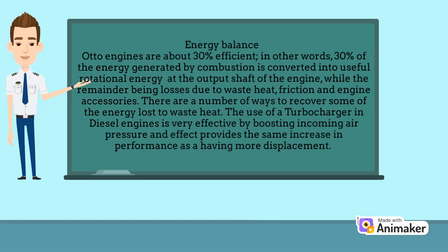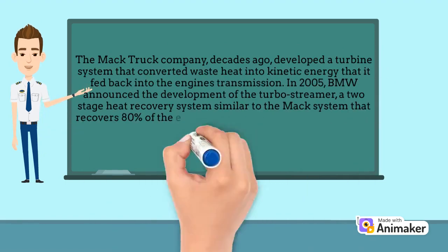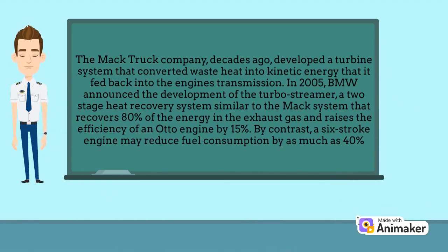There are a number of ways to recover some of the energy lost to waste heat. Use of a turbocharger, as in diesel engines, is very effective by boosting incoming air pressure and in effect provides the same increase in performance as having more displacement. The Mack Truck Company, decades ago, developed a turbine system that converted waste heat into kinetic energy that it fed back into the engine's transmission.